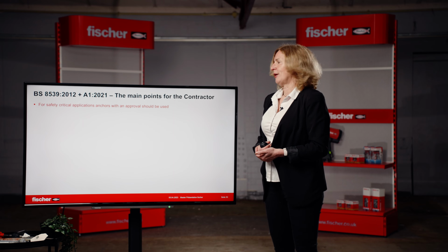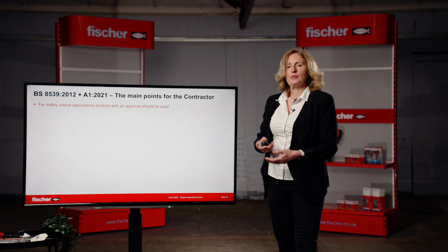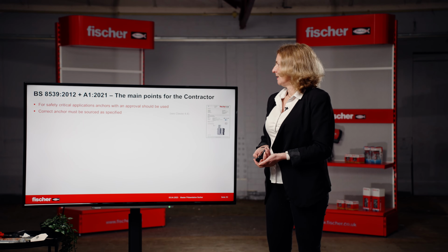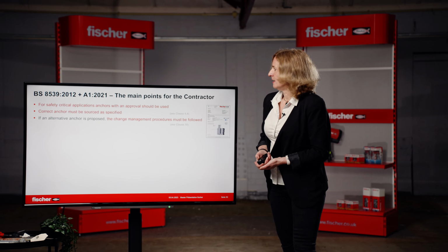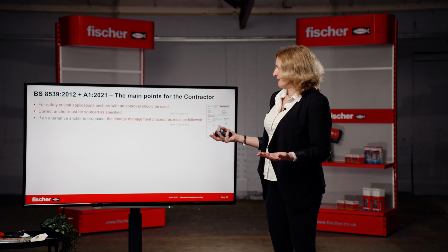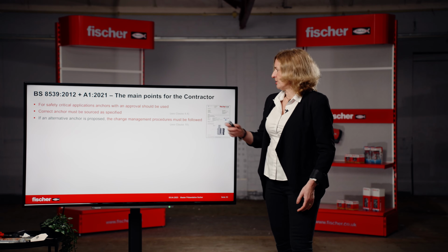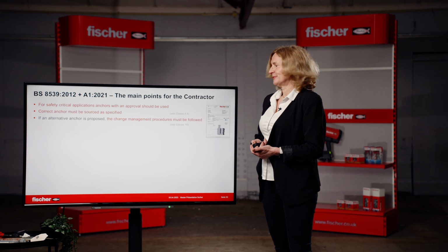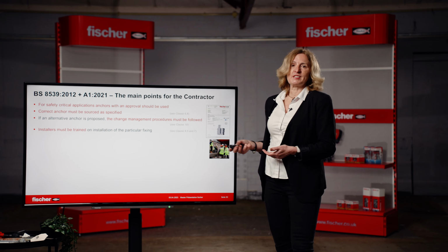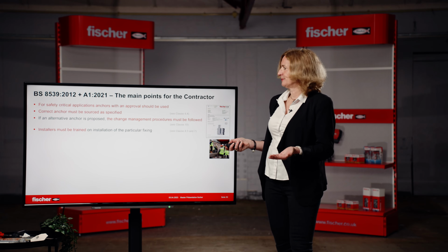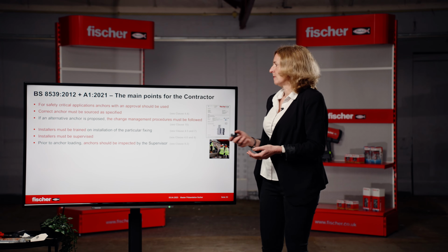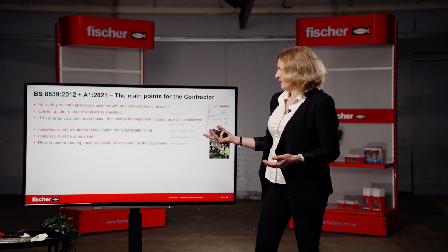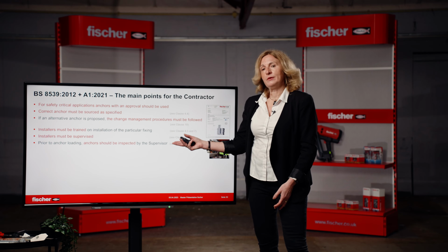For safety critical application, you have to use products with an approval. Correct anchor must be sourced as specified. If you are using alternative anchor, change management procedures must be followed. Installers must be competent and trained. Installers should be supervised. Prior to anchor loading, anchor should be inspected by the supervisor.